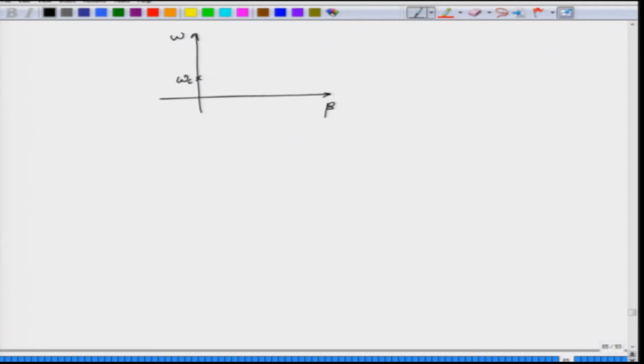So, until this cutoff frequency occurs, the value of beta will be imaginary, and I am not representing that in this axis, okay. But once omega starts to increase from omega c, beta will actually start to increase, okay. In the asymptotic case, this is the kind of asymptote which I should actually write in this manner, okay. The ratio at any point, the ratio of omega to beta, so this is some omega 0, this is some beta 0, the ratio of these will give you up.